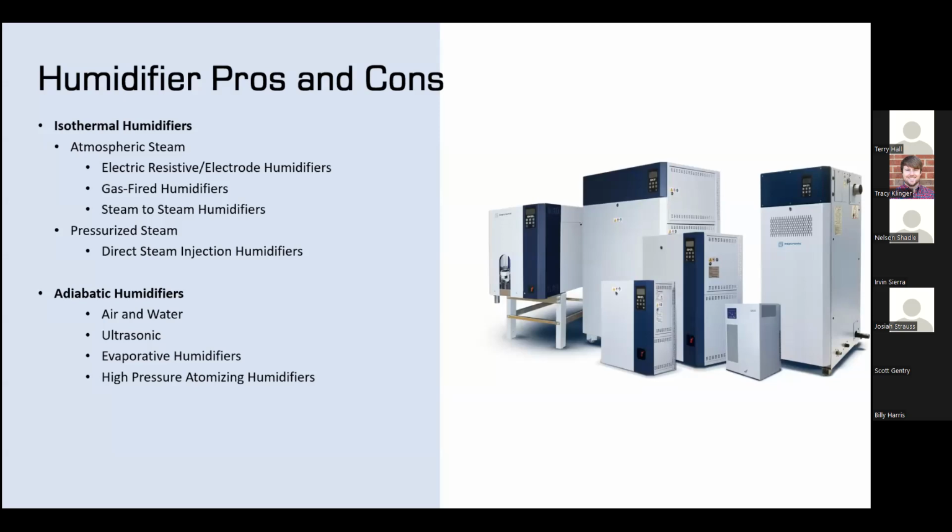And then there's also adiabatic humidifiers. So that's where we're using the ambient air to vaporize the water, and we're going to have cooling associated with that. So the issue with that is that it may not play well in your environment. If your environment's already humid, it's not going to work ideally. However, if you're generating a lot of heat through a process, those might be better because you can take advantage of that heat and then get free cooling.